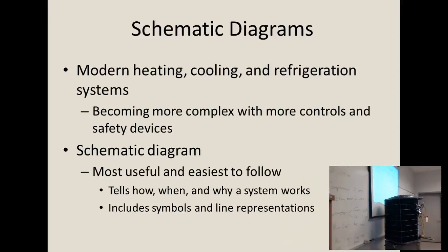All right, so I'm going to give you 5 steps here. I would highly recommend you write them down. Step 1, all line voltage. Now y'all, this is considered line voltage. If it's not line voltage, what kind of voltage is it? Low. It's load side, but what other voltages do we have besides line voltage? Line voltage isn't necessarily 120 or 208, 230, 240. It's not control voltage. In our case, control voltage is 24 volts. So everything that's not control voltage is line voltage. So all line voltage,